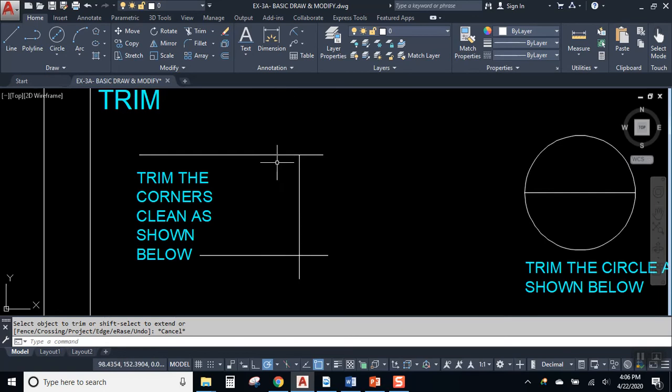All right, so let's talk about trim. I'm going to click on trim, and I want to get rid of this part of that horizontal line. How can I do it? Well, remember, it's asking you, where do you want to stop? See, I want this line to stop here, so I'm going to select this one. And then I'll hit enter. Phase 1 just ended. Select. Now I'm in phase 2. Execute. Which side am I going to get rid of? That side or that side? See, I want to get rid of that side.